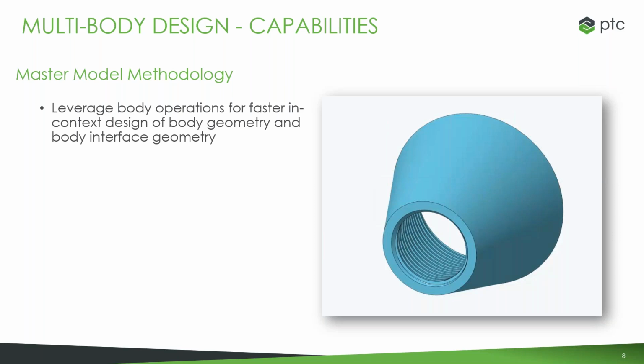I know there are a lot of mid-range CAD systems out there, and their approach to top-down design is all but nothing multi-body, even as of today, because they don't have powerful features like skeleton modeling, published geometry or copy geom, and tools to control them in a structured manner. Creo top-down design is the best in class, and it's a very smart and unique way of creating a very well-disciplined structured assembly where you can control, document and plan your design properly.